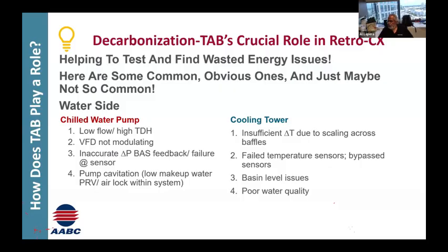Right. The only time I think you and I are ever going to disagree: I hate triple duty valves. I absolutely hate them with a passion. When an owner has told me they want to put them in, I make them put a valve above the triple duty valve, otherwise there's no way to replace it without draining the system. Yep. I'd rather just put in a balancing valve. That's just me, from my experience.